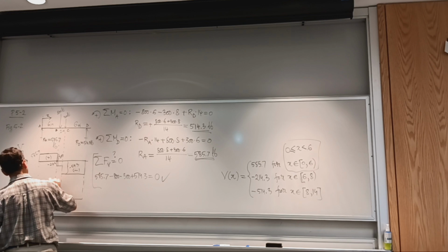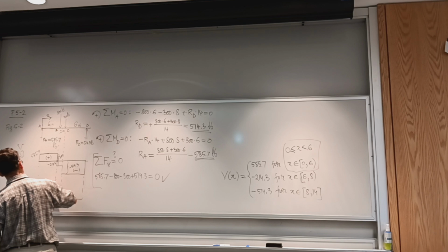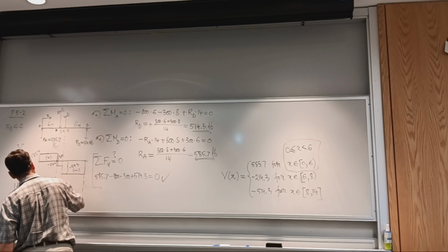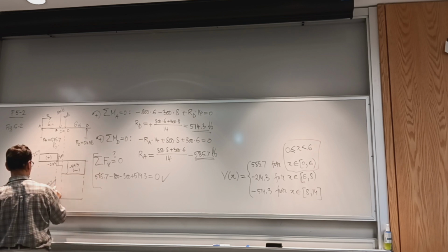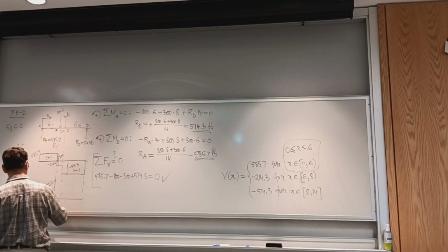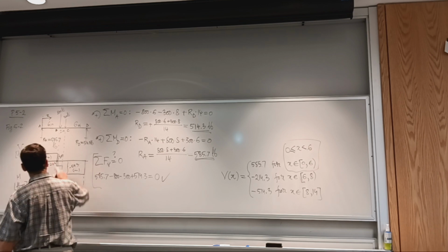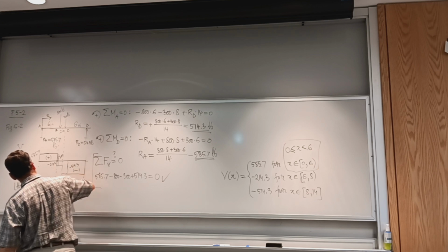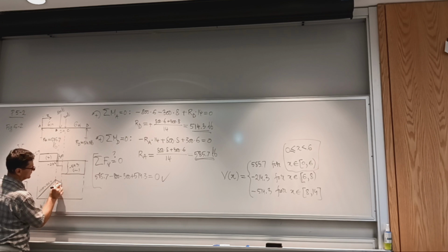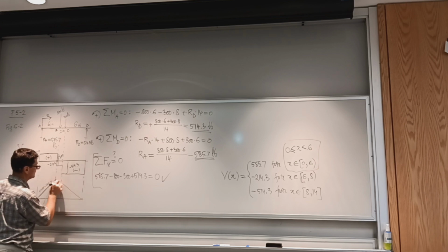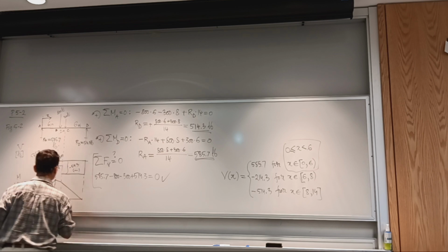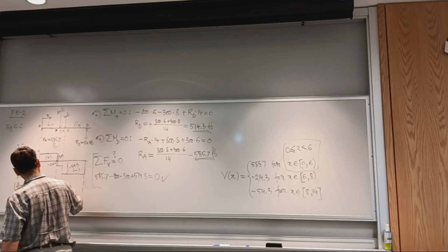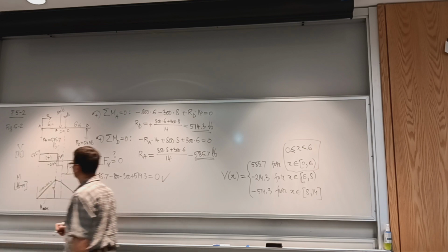Okay, so I draw a straight line. And the slope here, you don't need to write this. The slope is going to be 585.7. And it's going to reach the maximum. And sometimes it is useful to put it on the drawing. So M max, we know it's going to be a max because then the slope changes to negative 214.3. And there's another drop, let me make this shallower to where you can see the difference clearly. All right. So this will be the maximum. I know it's aligned with 0 in the shear diagram.